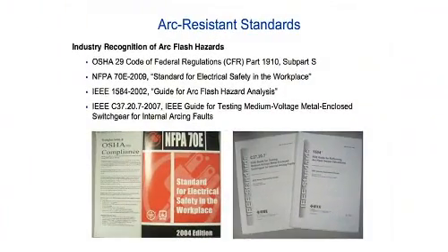Okay? So what C does is it isolates between each of the compartments. In other words, if a fault should occur in the lower breaker compartment, and say in two-high switchgear, and you had an upper breaker, lo and behold, it would not migrate to the upper breaker or a PT compartment next to it. In other words, we isolated the fault to only that compartment that was impacted. This allowed the rest of the switchgear to operate correctly.